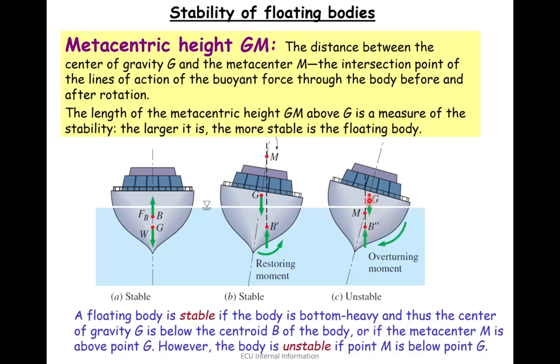Why? Because if you turn the vessel this way, you can see the turning moment is also acting this way, so the object is unstable, because the turning moment and the turning of the vessel are in the same direction. However, for this one, when you turn the vessel here, a turning moment acts the other way. You see the turning moment acting anti-clockwise, which is obviously due to this center of buoyancy and metacentric height. So this is how important a metacentric height is.